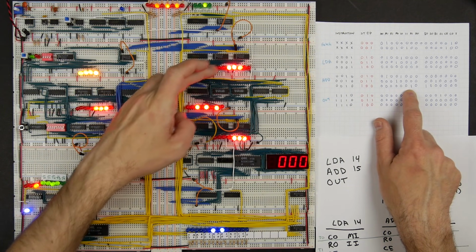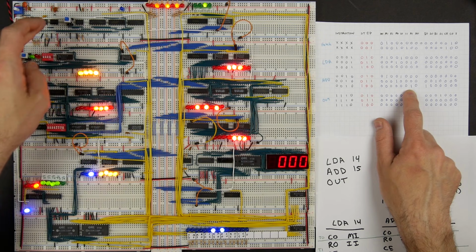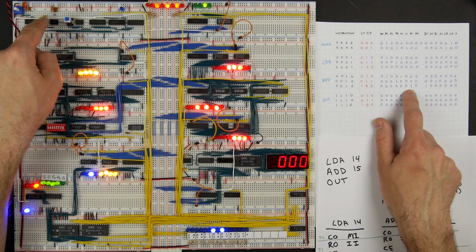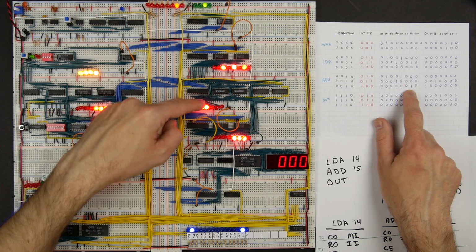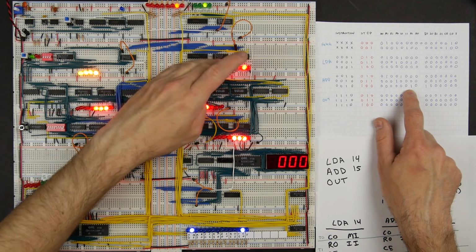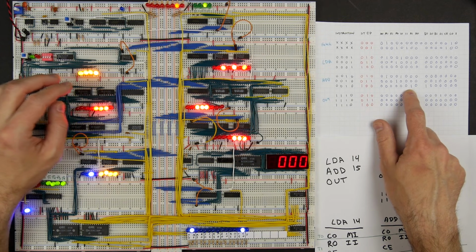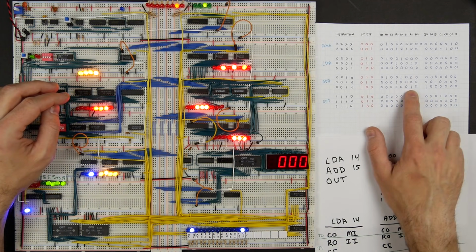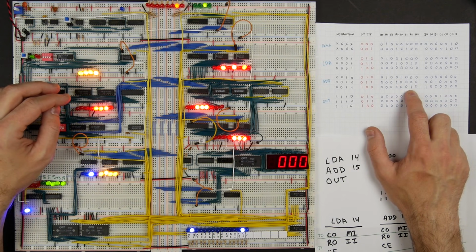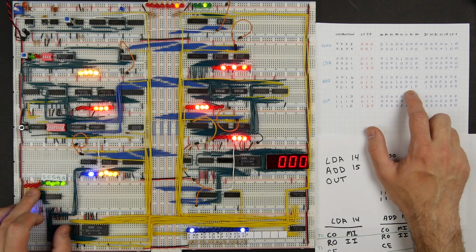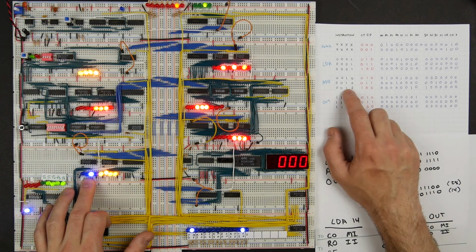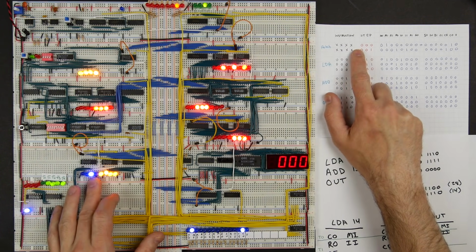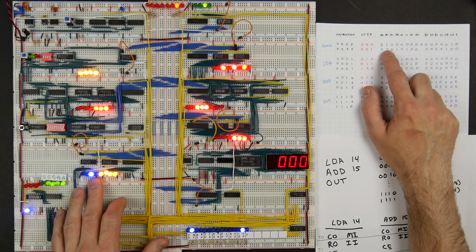And of course, it latches that into the A register just immediately on the rising edge of the clock. So as soon as that goes in here, it'll latch. And then, of course, now the new sum is there, but we've only latched it into the A register, so we have the sum of those values. And that actually used up all of our clock cycles for our instruction cycle, and so we're back at step 0 again. But now, our instruction is still saying add, but we don't care. We're in step 0, so we don't care what the instruction is. We're going to fetch the next instruction.